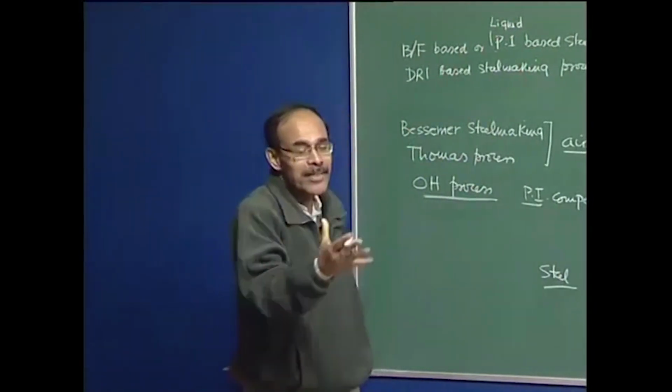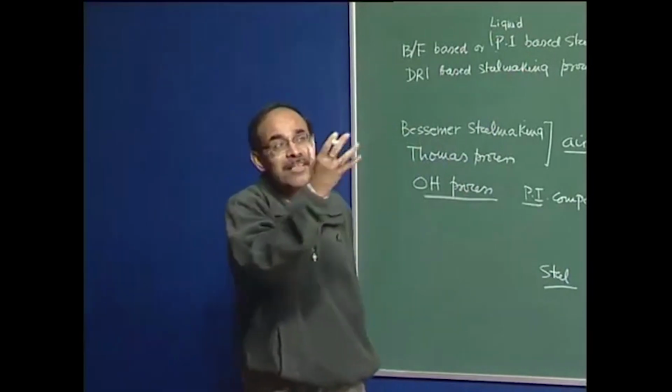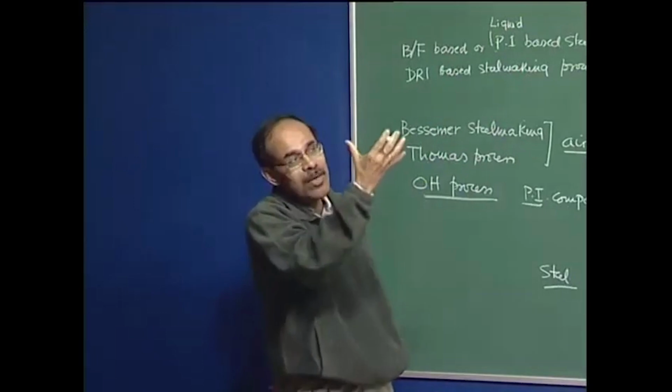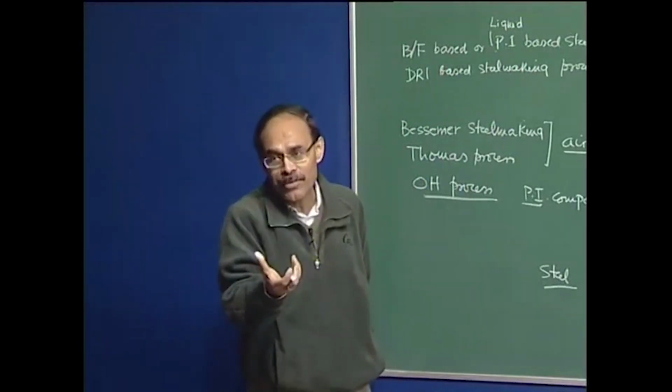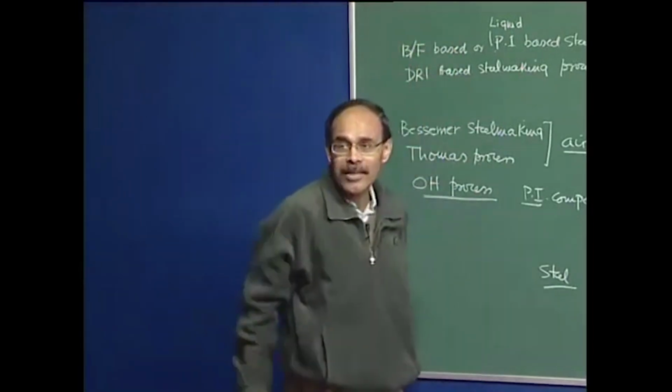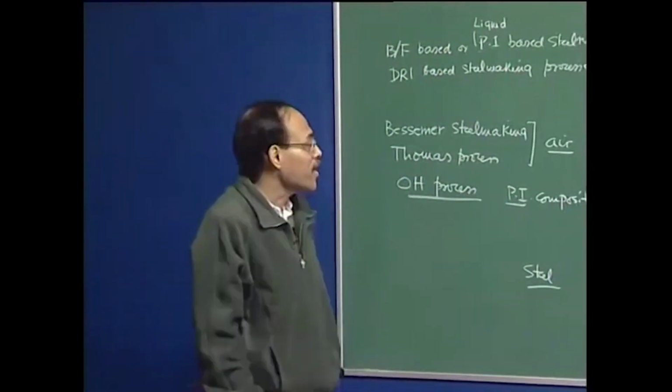If more volume of air is introduced, that means more heat is going to be consumed by the cold air, and you are also introducing more nitrogen, and this nitrogen, without doing anything, goes out of the steel converter. Therefore, it is going to take away heat.